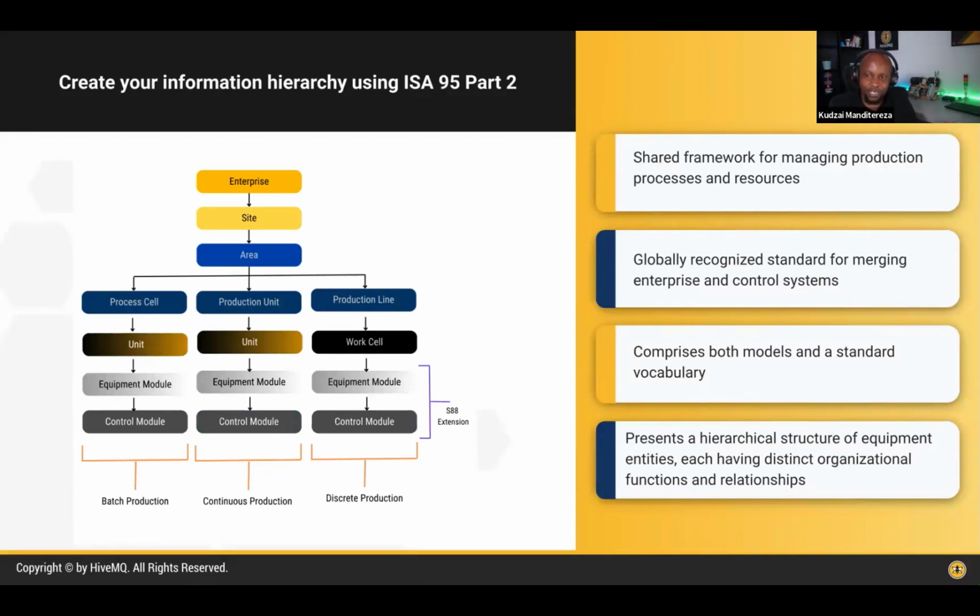How do you go about structuring all this data that you've been collecting in a way that makes sense across your entire enterprise for real-time consumption? And by the way, once you have the unified namespace as your real-time source of information, you'd still need some external data store. That external data store would still subscribe to that real-time data, that real-time snapshot of your enterprise, and persist that information for later use or later retrieval.